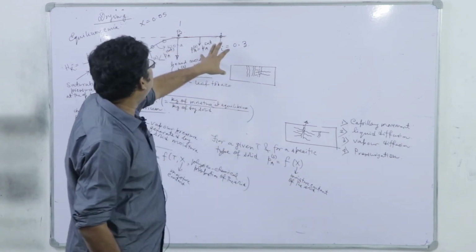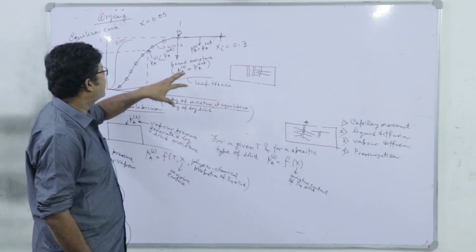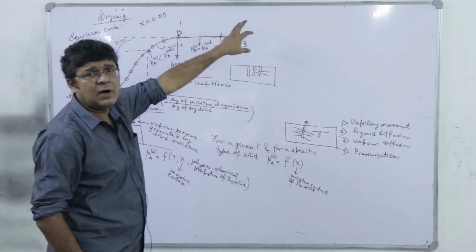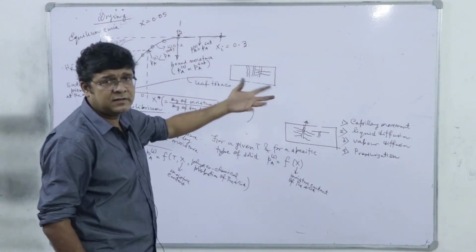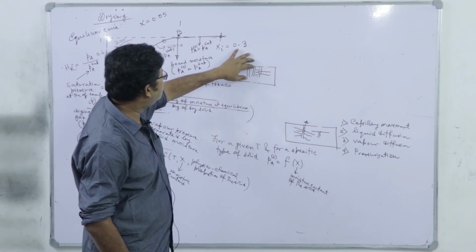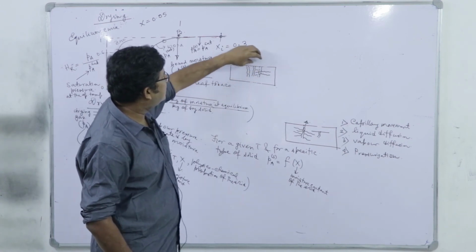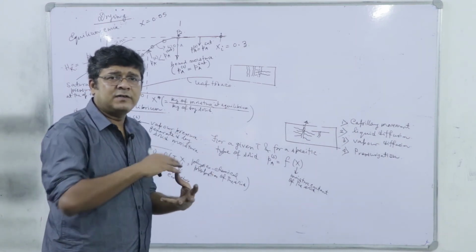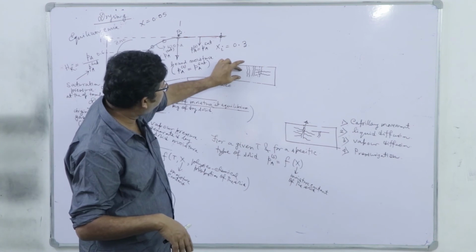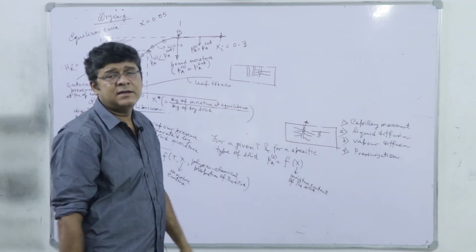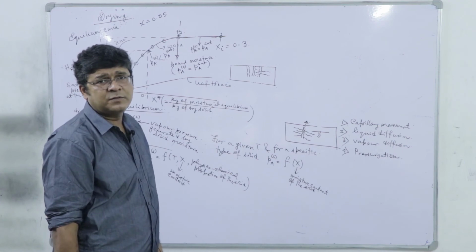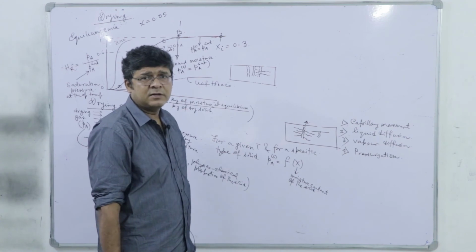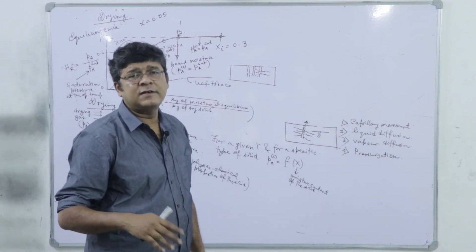Whereas, above and over this bound moisture, what do we refer to? We refer to this moisture content above the bound moisture as unbound moisture. As the name suggests, if we have an external film, the intermolecular interactions between the water in the film and the wood fibers are practically null and void, right. There is no specific interaction, as the thickness of the film is in the order of millimeter. So, we will call that moisture unbound moisture.